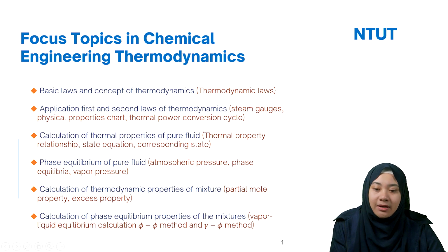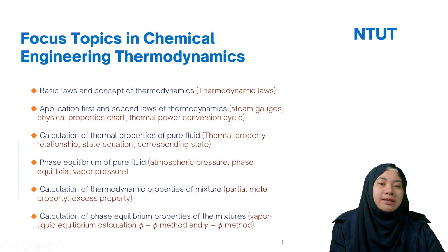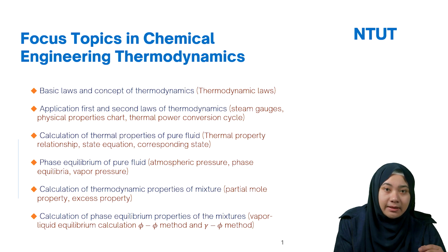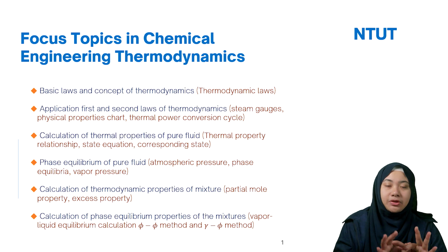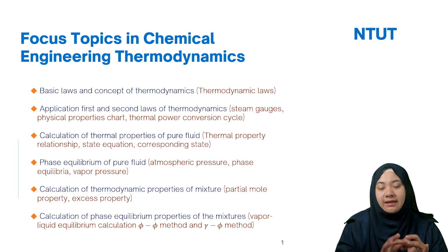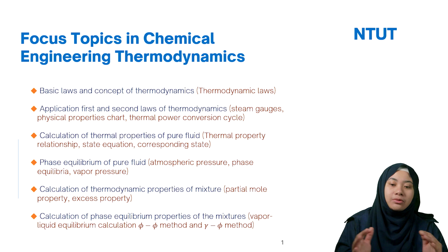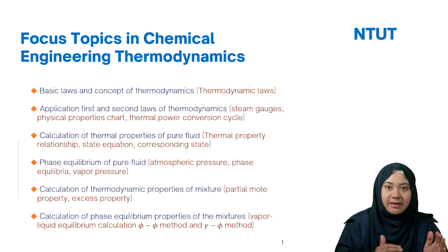And the other is equations of state. So what's the important equation here? Not everything in thermodynamics we can calculate based on calculations. Of course we need the experimental data. So mostly in the experimental data you will get the pressure, temperature, and the volume. So this is PVT, we call it, the measurable variables. So when you would like to calculate the specific pressures, of course you need to have the experimental data.